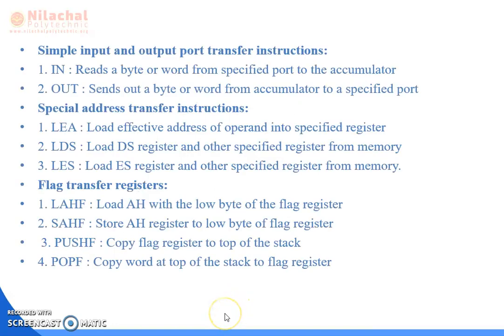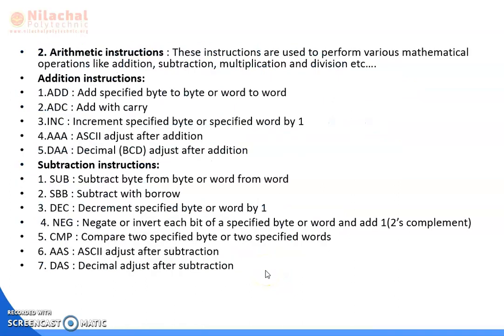Hello students, so today we are going to discuss the flag transfer register instructions. First one is LAHF, that is load AH with the low byte of the flag register. Then SAHF, that means store AH register to low byte of the flag register. Then PUSHF means copy flag register to top of the stack. POPF means copy word at top of the stack to flag register.